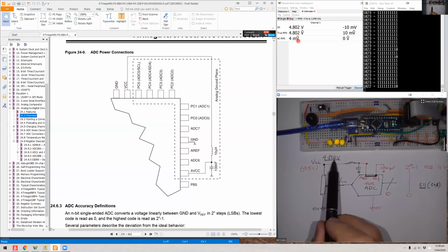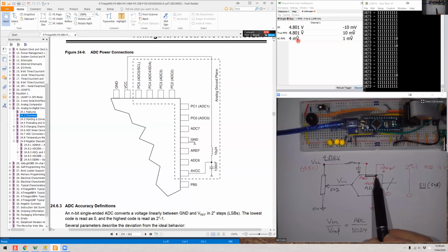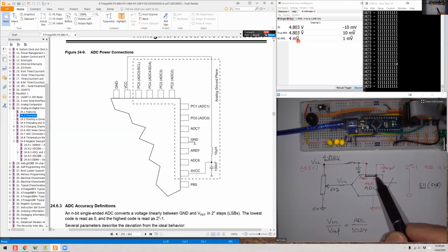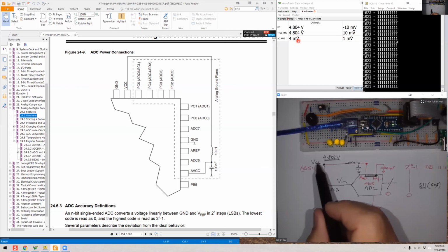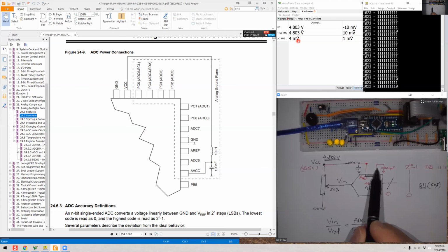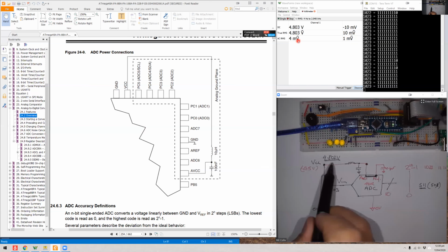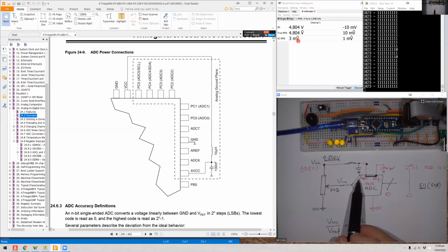Now, if our voltage changes, then our reference voltage will change. But this won't change at all, because this voltage here also changes. If this went to 5 volts, up by 0.2 volts, then this would go up by 50% of that, which would be 0.1 volt. And of course the reference voltage has gone up by 0.2, so the output here won't change at all. So this is how this simple ratio protects us from any fluctuations in voltage. Though it is a better idea to make sure we're filtering this so that we don't get noise on the supply causing problems.